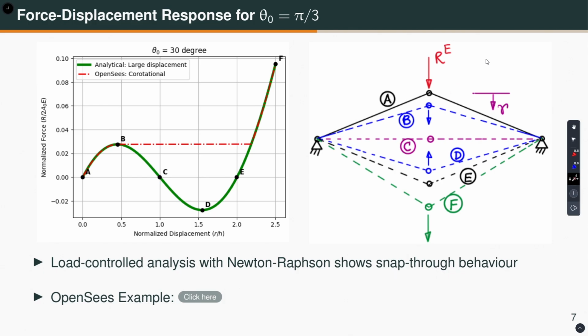Let us first talk about it in reality. So, you have this kind of an arch with two members, right, and you keep on increasing load. So what will happen? The structure will start to take more and more load, more and more load. So you will go along this path, right, up to the point that is called the limit point, right? So if you keep increasing, put a little bit more load, what will happen? Well, beyond this, it cannot go.